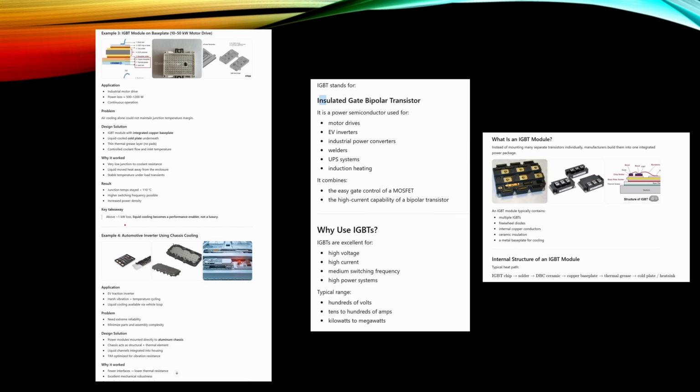Another example is this kind of automotive inverter, and in this case the main requirement is that it needs to be extremely reliable, and of course we want a minimum number of parts and easy assembly. The good design solution is that we use an aluminium chassis and we have liquid channels integrated into this house.